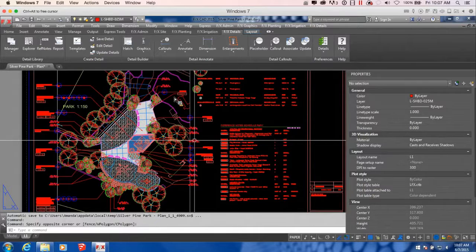So I'm going to make a new layout, and I'm going to do this in a different drawing as opposed to just a different tab in this drawing, like we've been recommending in our sheet setup webinars. And if you've submitted a support ticket, we've probably recommended it as well. It just keeps things separate so that multiple people can work on the project and keeps files smaller. It also prevents the total meltdown of your mind if something goes wrong and one drawing gets corrupted and crashes CAD and you can't reopen it. At least it's just one drawing that you're having to recreate in that situation.